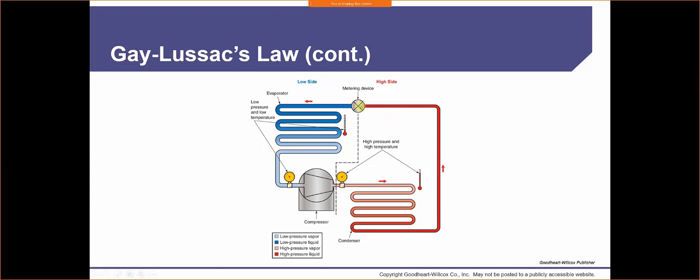So we've got this cold liquid, all right, that's traveling through our evaporator. The evaporator is going to be the unit that sits inside your house. It's going to sit either above or below your furnace. And so that refrigerant is going to come through in a liquid state, right? As we start to make our way through the evaporator, warm air gets blown across it. Okay, we've got warm air in the house that's hitting this evaporator. The heat starts to be absorbed into the refrigerant.